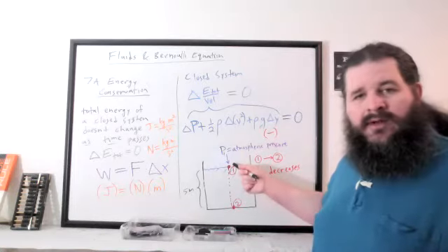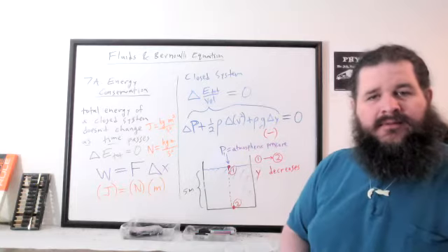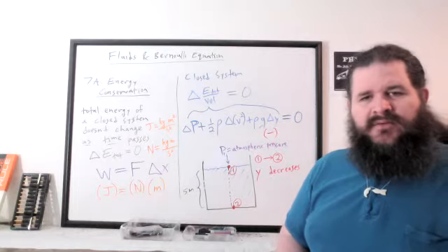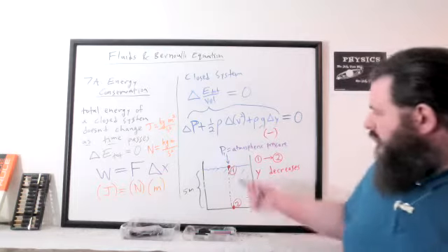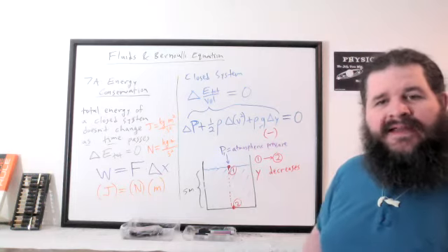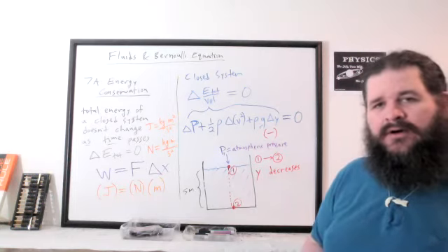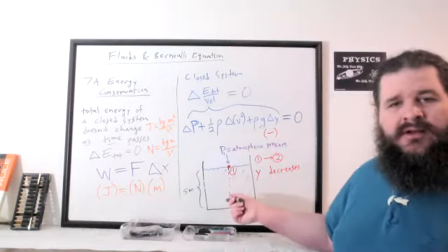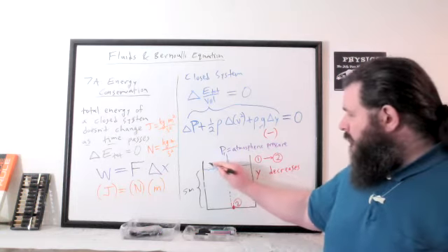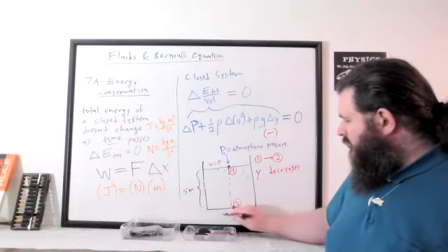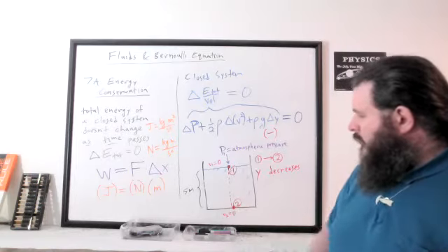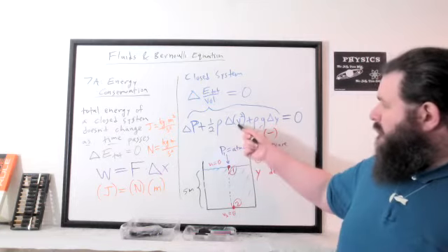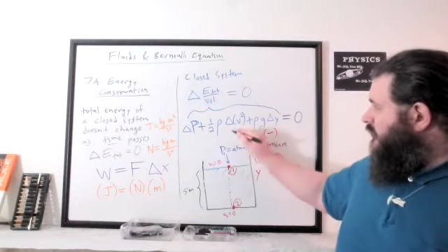What's the speed of the fluid at point 1 and what's the speed of the fluid at point 2? Is this fluid moving? Yeah, there's no change. This fluid is not moving. It's what we would call a hydrostatic system. Hydro meaning water, static meaning stationary, not moving. In a hydrostatic system, there's no motion. So the speed 1 is 0, and speed 2 is also 0. But the thing is, it's not really important that it's not moving. The important thing is there's no change. Speed 1 and speed 2 are the same value, so there's no change in speed.